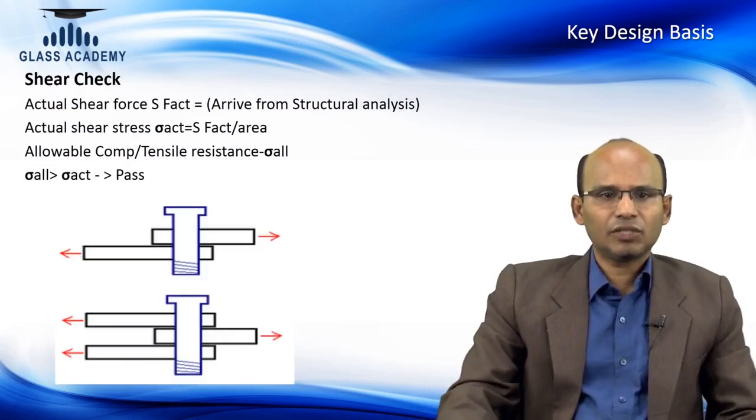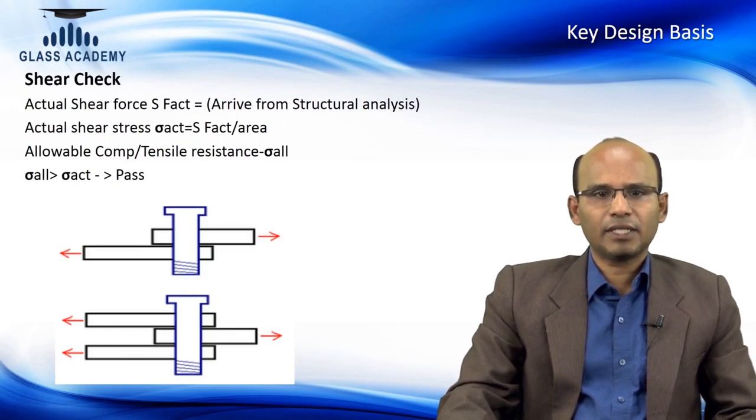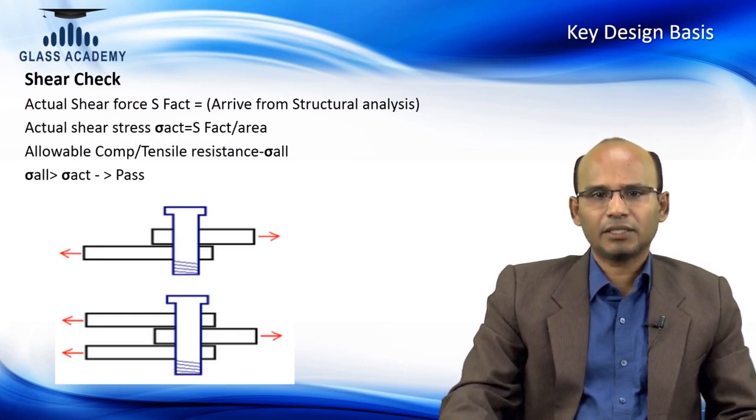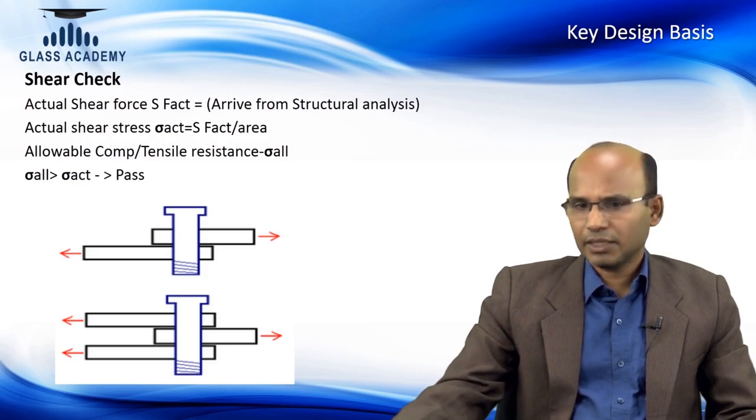Shear check is generally done for connections and brackets, where large loads are transferred through a small component, where this kind of shear stress is critical. This is critical especially if using aluminum brackets. Aluminum brackets have slightly lower bearing stress and bending stress compared to steel. So, this check is critical for facade and glazing applications.